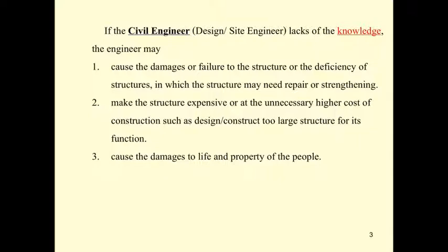For example, if you design the structure with concrete with the strength of 32 megapascal, or 320 kilogram per square centimeter, and the concrete seller sends you low-strength concrete, let's say 240 kilogram per square centimeter or 20 megapascal, what will happen?